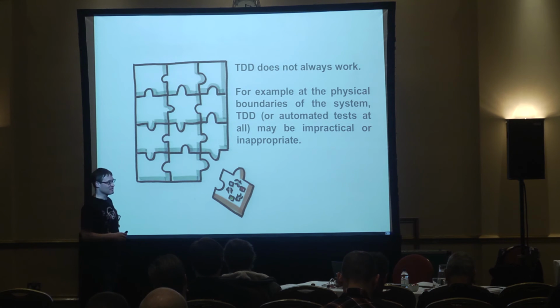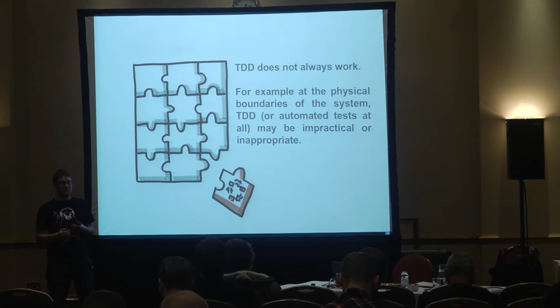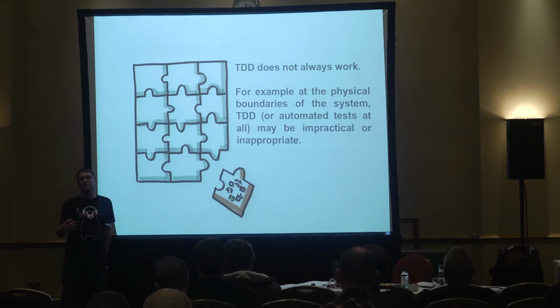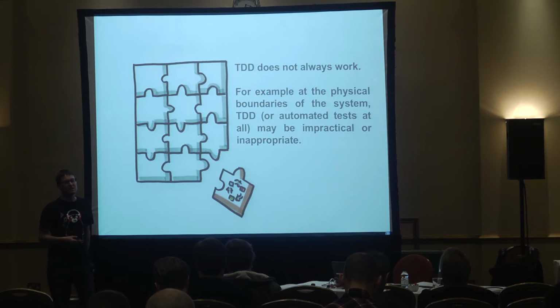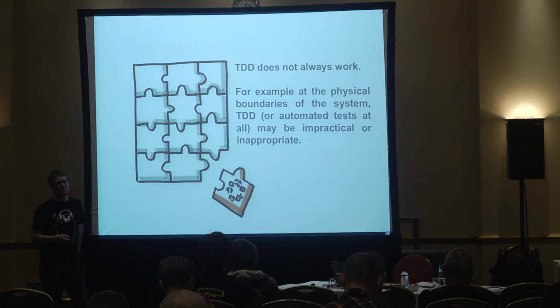Then some disclaimer that sometimes TDD is not really that appropriate. Before, I showed you these registers that were in the test, so the test really goes to the hardware boundary. For a GPIO device, it works quite fine to do TDD on that level. If you're maybe implementing a USB driver on an ARM, there you have a set of about 10, 20 or 30 registers that you have to care about. Then maybe it works, maybe not. I still don't really have the experience to tell how far you should go and whether it really makes sense or not. Sometimes you have the stuff that you can do, but it doesn't always mean that it's the appropriate thing to do.